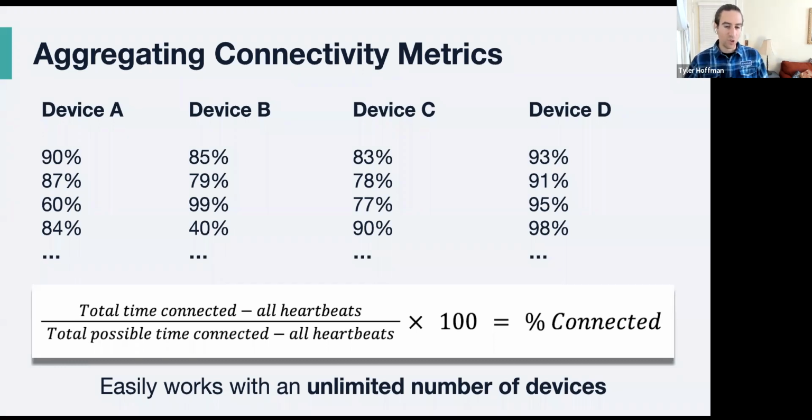We said, generally, given the way our customers use our devices, they're 90% connected. If that dropped to 80%, for instance, we knew there was probably a Bluetooth bug. It wasn't that our users just dramatically changed the way they behave overnight. It was a regression. Or if our devices were spending most of their time scanning, or it ticked up 5% in scanning time, we knew there was probably an issue in our Bluetooth driver.